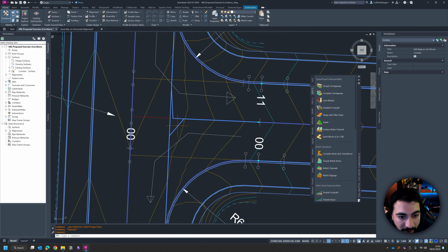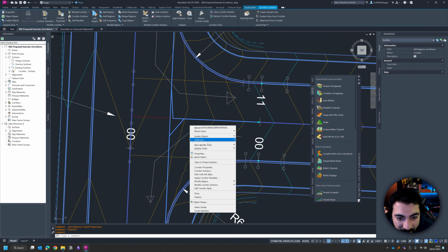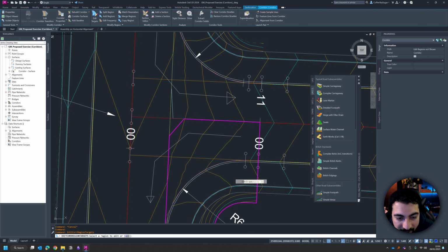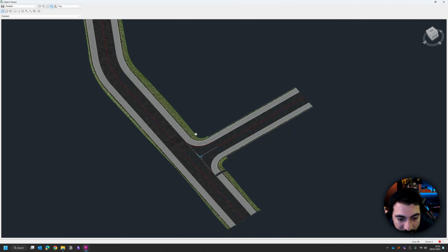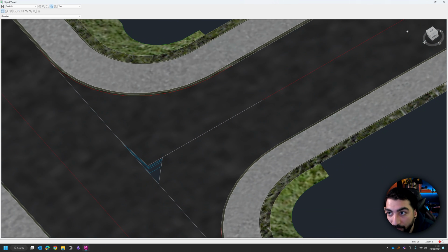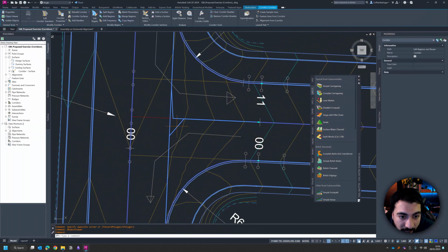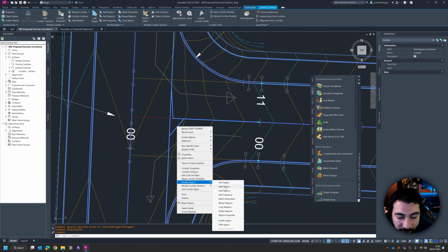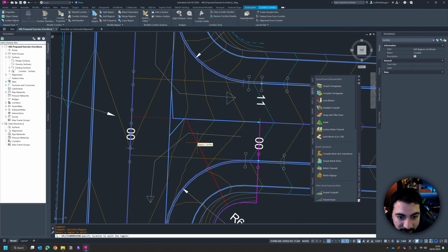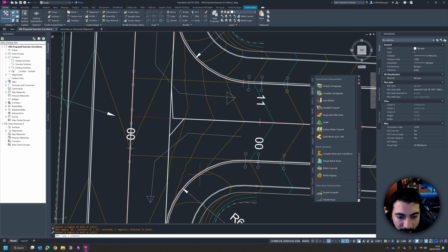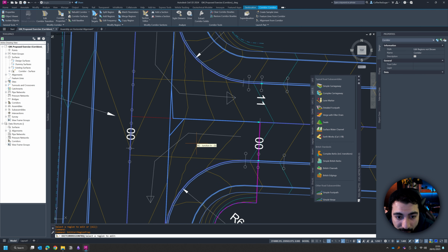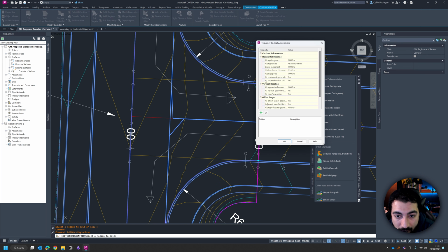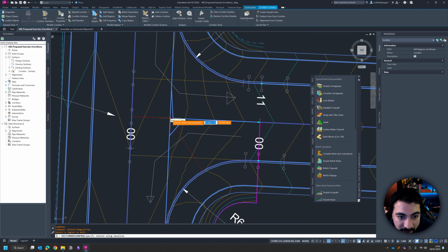And it's done. You can see we have this little gap here, and that can become evident when you start doing things like edit targets. You can see there's a gap here, and you can see it also in the object viewer. So that gap can be fixed two ways. Either you split the region and say, I want to split it right there. Or the quickest trick that I found is to right click, modify region, edit frequency, and then in the plus icon here, just target that point.